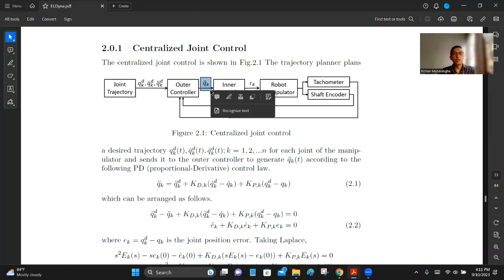Okay. And already it knows the joint position and joint velocities, existing ones. So using existing joint velocities, you can calculate the Coriolis and centripetal forces. And using the joint positions right now, you can calculate the gravity terms, right? But in order for you to calculate actual torques required, you need the inertial terms in the dynamic model. And that can be calculated only if you know the angular acceleration. And for that, you have this one, Q double dot K, right?